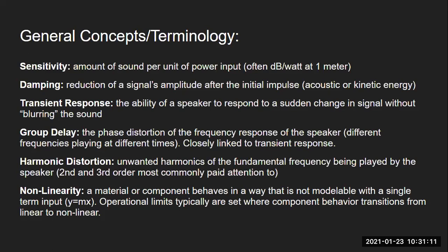So generally, even outside of audio, this is a huge consideration. It is what is the fundamental frequency of an object, and how do we avoid hitting any frequencies which will cause it to do that, because there are multiple orders of this. And so generally when you're designing, you're only considering the second and third order, just because that's the most likely ones to hit beyond the initial frequency.